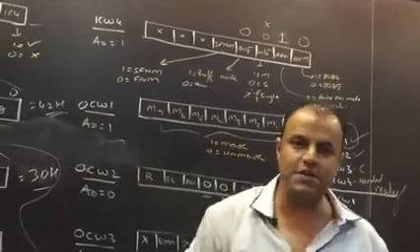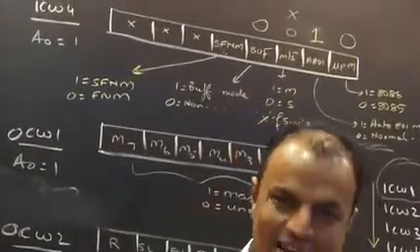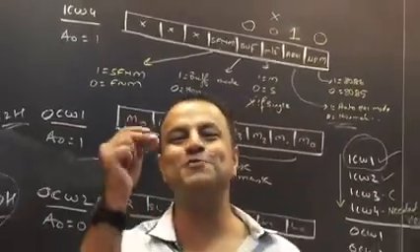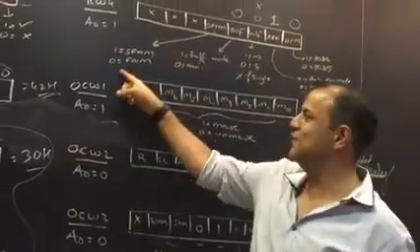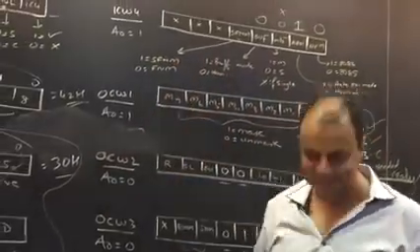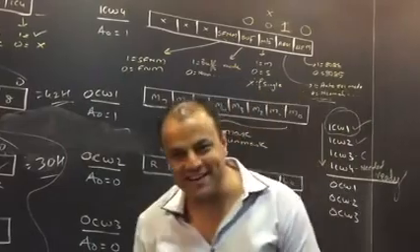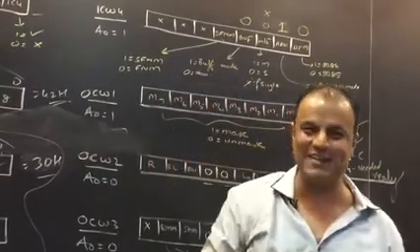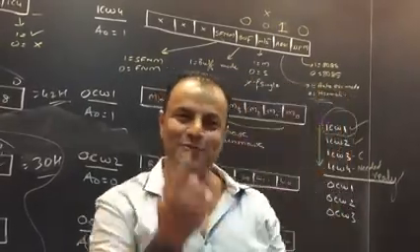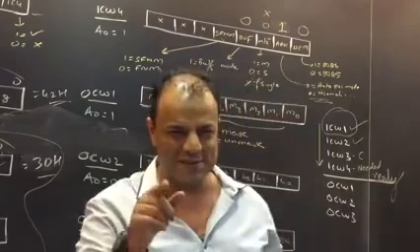SFNM, special fully nested mode. You remember priority modes? The default priority mode is which one? FNM. So 0 is FNM, 1 is SFNM. SFNM is used only in cascaded 8259s. If you want the definition, in SFNM, the master will recognize a new interrupt from a slave whose another interrupt is already being serviced. Do you remember that?